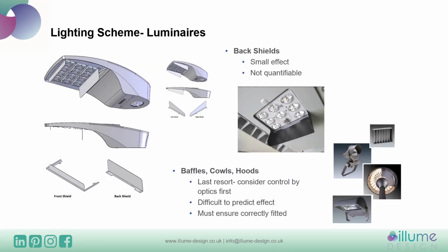The other problem is that they're not quantifiable. So where I talked about photometric data, that's the data that we use in lighting software to predict the impacts from the light sources. But if you don't have the data for the backshield, we can't model that and show the impact on a lux contour plan.